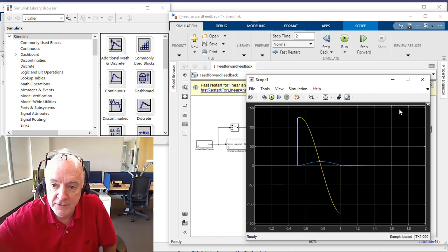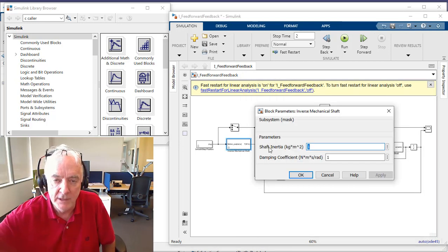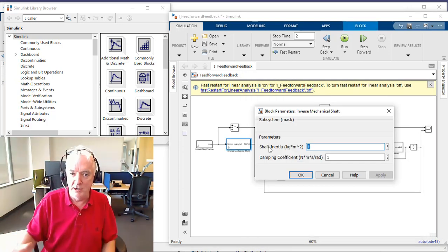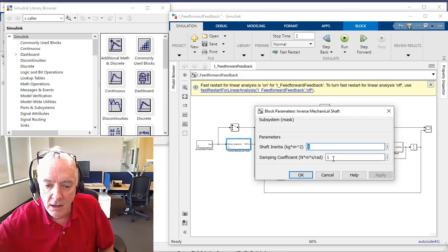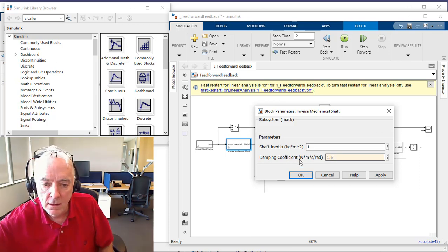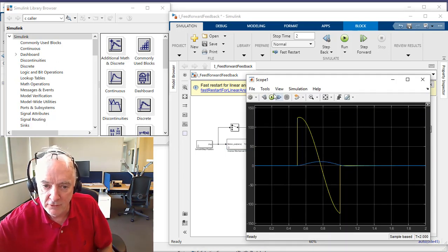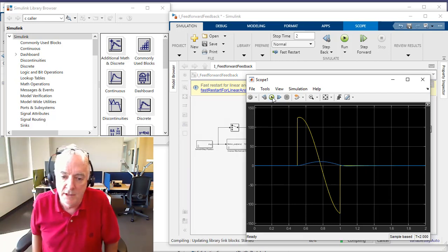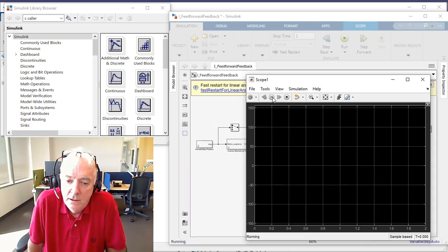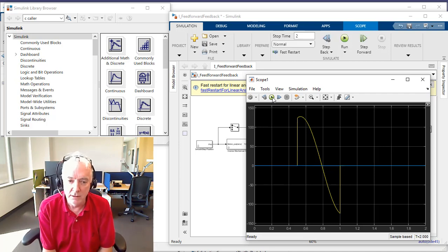And to emphasize that point, if my knowledge is perfect of what the equipment is, which is generally operating in a nominal state, okay, so my feed forward controller is now matching the actual equipment, you'll see that your feedback will be nearly zero compared to your feed forward component, right?